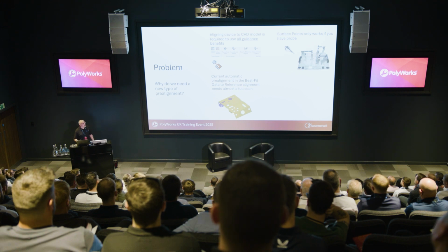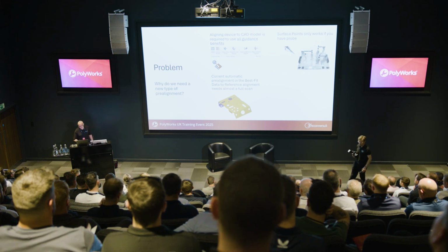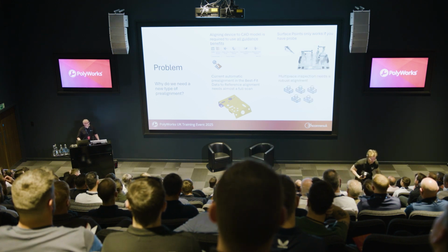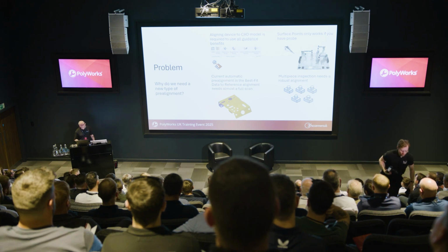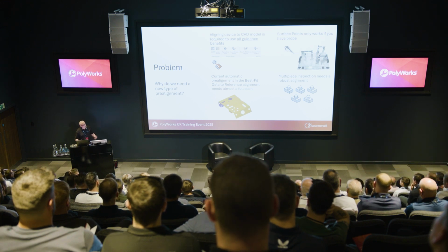The current best fit data to reference that we have requires nearly all of the data before it can actually do that alignment, which means that you can't do your scanning guidance, because by the time you've got all your data it's too late, and that's the point at which the alignment gets done. And then if we're wanting to go into multi-piece inspection, then we need that robust alignment so that when we bring in the new piece, we can do that same alignment and get exactly the same every time.